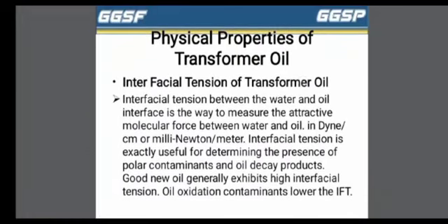Physical properties of transformer oil. Interfacial tension of transformer oil. Interfacial tension between the water and oil interface is the way to measure the attractive molecular force between the water and oil in dyne per centimeter or millinewton per meter.